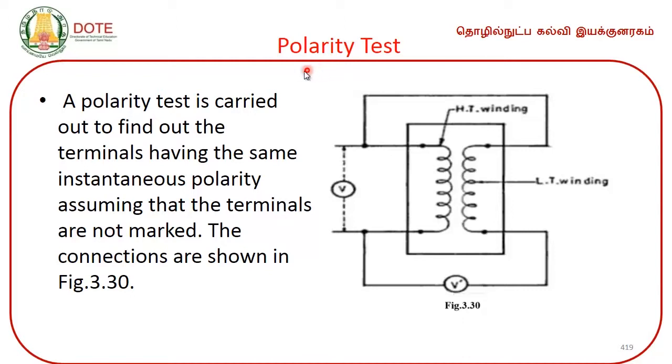Then comes the polarity test. A polarity test is carried out to find out the terminals having the same instantaneous polarity, assuming that the terminals are not marked.